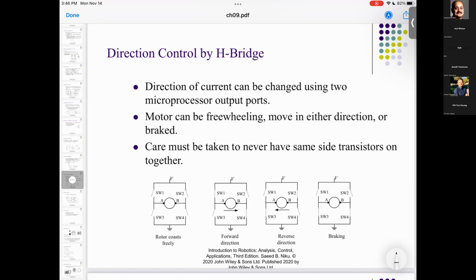No, I didn't make any changes anywhere at this point. This is the ODE1 M file that was generated once you fed in your Lagrangian. All I did is add these notes. Y1 is angular displacement of joint 1, Y2 is angular velocity of joint 1, Y3 is the linear displacement of joint 2, Y4 is the linear velocity, Y5 is the angular displacement, and Y6 is the angular velocity. These are the only changes that I made to this code. Everyone with me so far? Yeah, you have to generate the ODE1 file using the Euler-Lagrange script, the way we did it for all the robots.